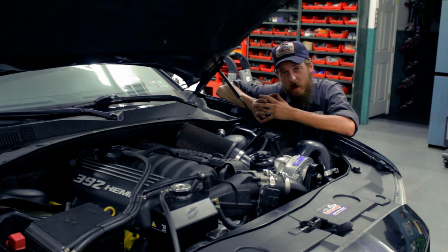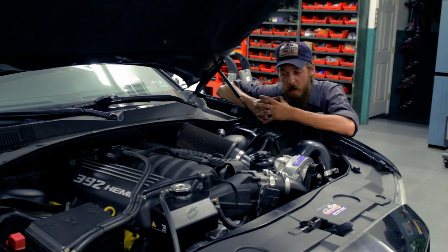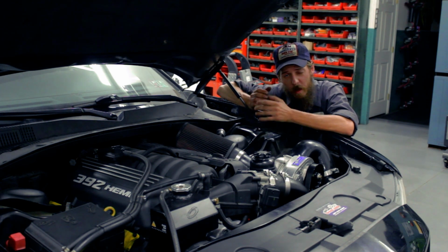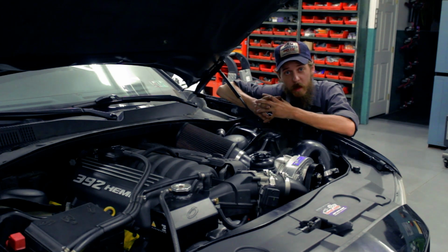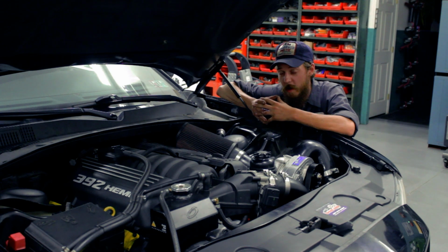The interesting thing is we look at how many different modules receive that park neutral input, something that we're very familiar with. Actually, I had a Nissan up in Staten Island a few months back, or almost a year ago, I guess, about now, that also utilized 2 park neutral switches, and they disagreed, and that created an intermittent no start, but not an intermittent no crank.